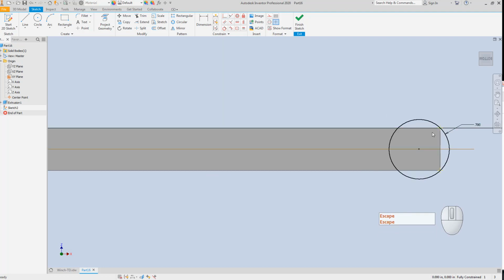it is passing, and I will add this addition here. Also, I made a mistake. You can also make tangent to this point with the curvature, which is this point and this point are on the same line. I use an aid line, a horizontal one, and make coincident this point on this line.